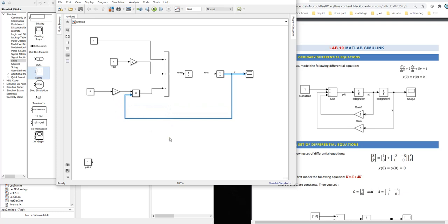Don't worry, Simulink will make a loop and try to find the value of y. But just to remind you, this is the y signal. Same thing for y dot. Where is y dot? We need y dot here. I will remove the y dot from here. It should not be a constant, it should be y dot.